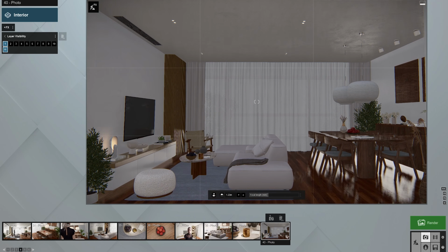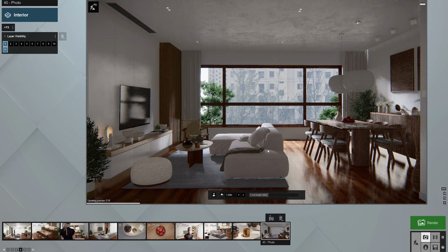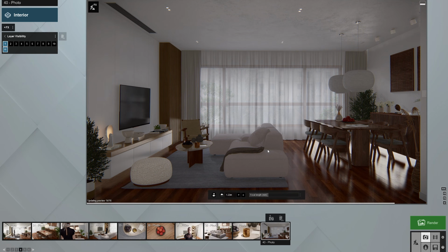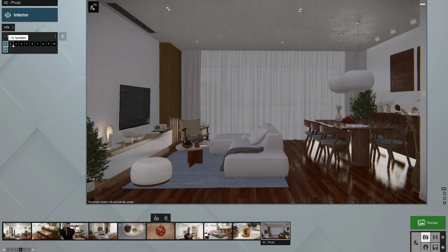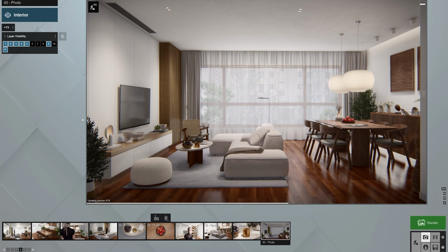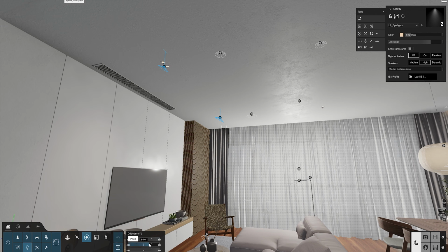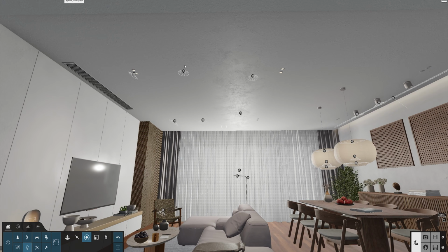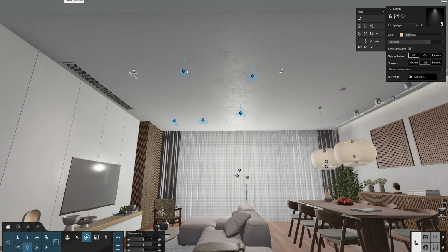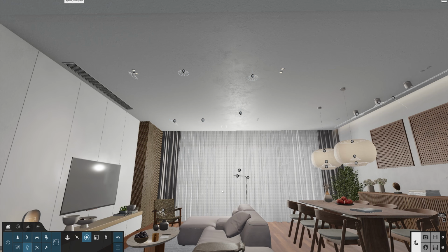One of the main problems I see when people try to create realistic interiors in Lumion is that they only rely on the daytime lighting, nothing else. You shouldn't be afraid of using artificial lighting to complement. With Lumion, it works quite well for interiors. Take this interior for example. I'm using spotlights for ceiling lights, and these 2 lights, I rotate them slightly to the wall, so we have more lighting detail on this same wall. You can see that these 2 lights are not exactly in the same place as the ceiling lights, but sometimes you need to fake it to have better results.